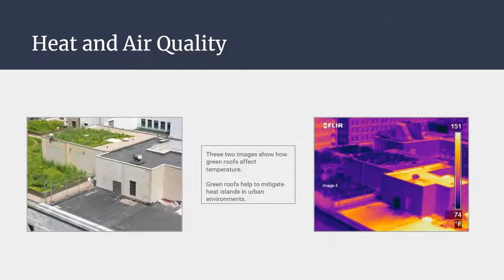Since a green roof reduces the temperature in the surrounding area, it could save billions of dollars every year in energy costs. This is true for different reasons. In summer, the green roof protects the building from direct solar heat, and in winter, the green roof minimizes heat loss through adding insulation on the roof.